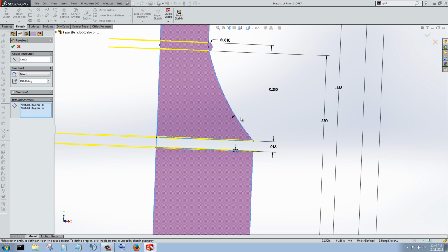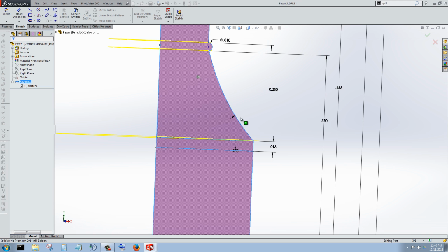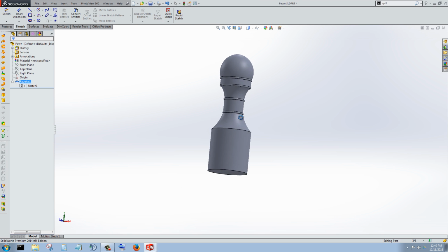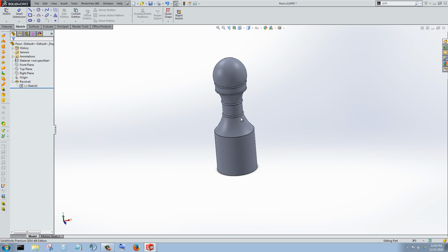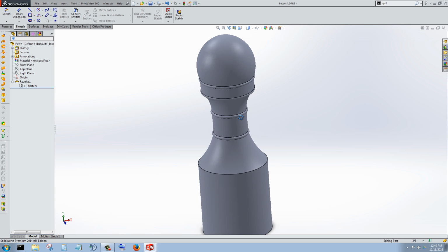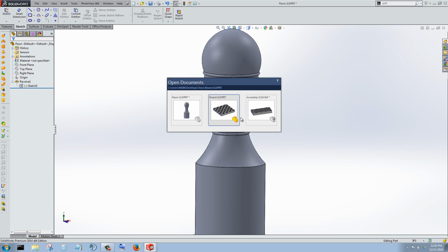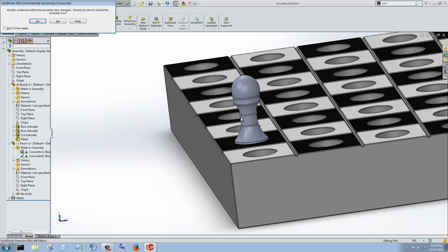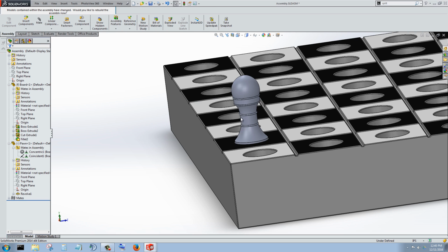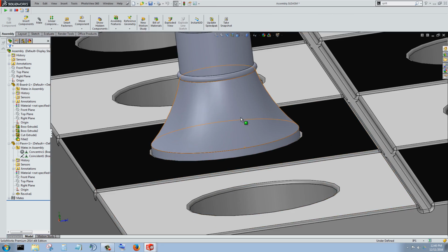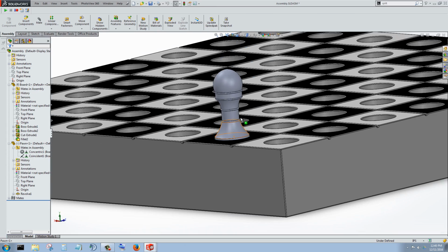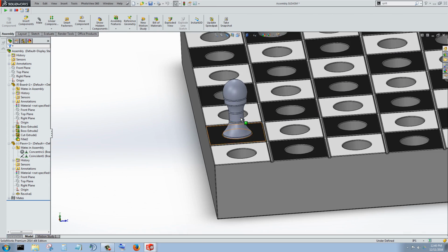So I just left click into selected contours, come over here, get that region that I just added, green check mark. And what I will do, and this will be interesting, is Control Tab over to the assembly. Would you like to rebuild the assembly now? Yes, rebuilding, and look, there it is. Cool. I feel better about that.